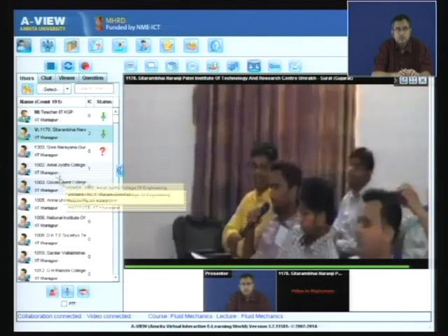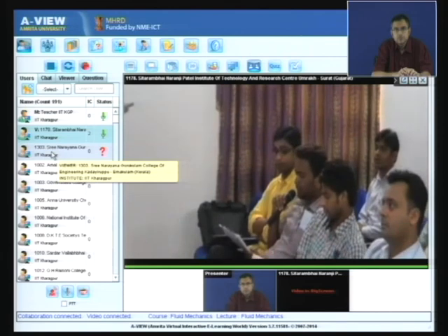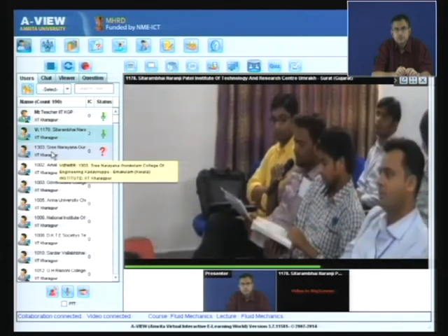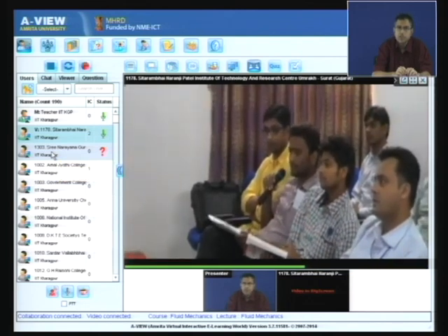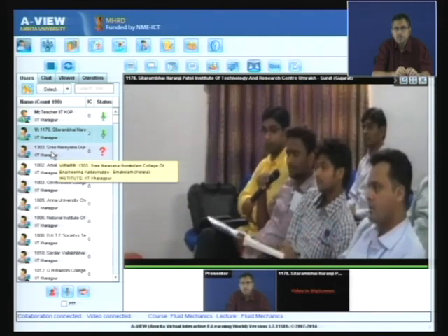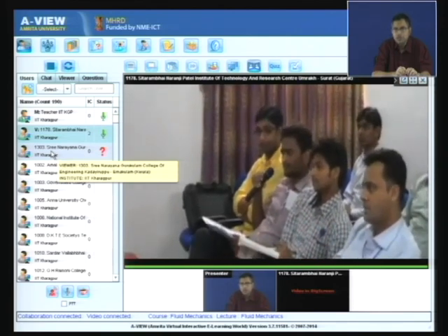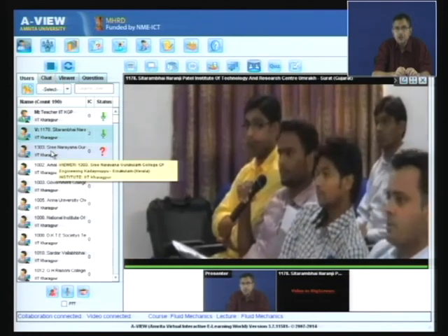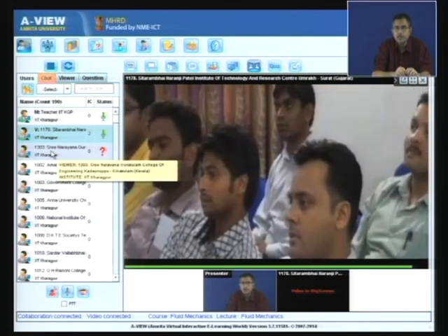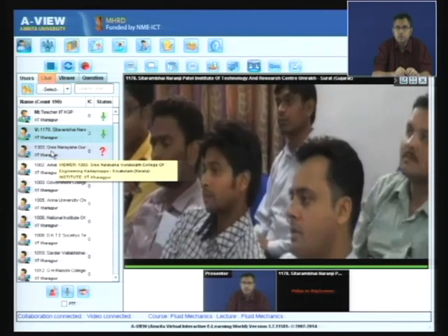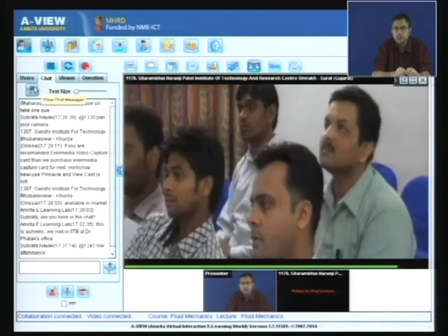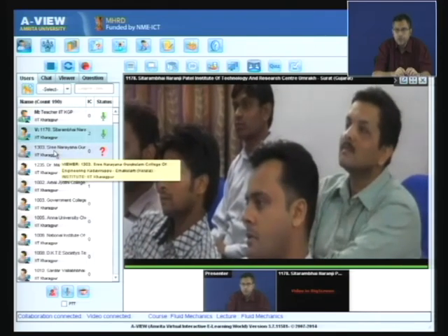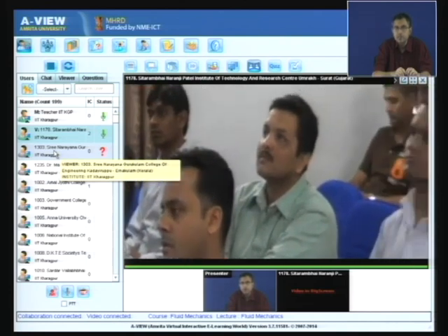My question is regarding the fully developed region. In the fully developed region, is the velocity profile always parabolic, or may it have any other profile? It may have any other profile. It depends on whether other body forces are present or not. With a pressure driven flow, the fully developed velocity profile is parabolic. But if you have other driving forces like electrical field, magnetic field, or several other types of driving forces driving the flow, then it is possible that the velocity profile in the fully developed region may not be parabolic. So, the fully developed velocity profile will be parabolic only when it is a pressure gradient driven flow.